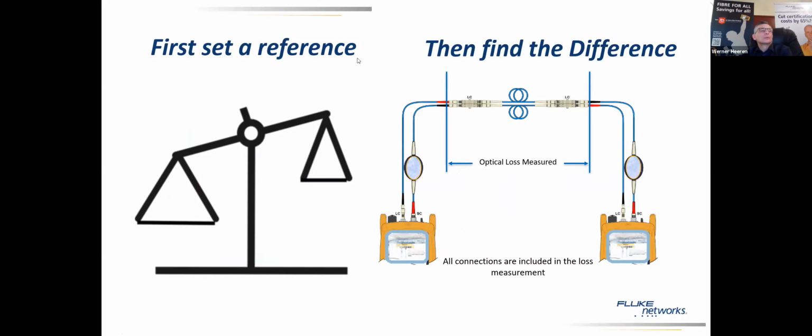In the meantime I saw the poll was stopped, so yeah, a lot of people are using an OTDR. You can use both. We know from experience, a lot of people still use an OTDR for certification also. And again, Weil will explain in an upcoming webinar that for certification, you should use an optical loss test set or light source power meter, and for troubleshooting, an OTDR. Thanks for the inputs.